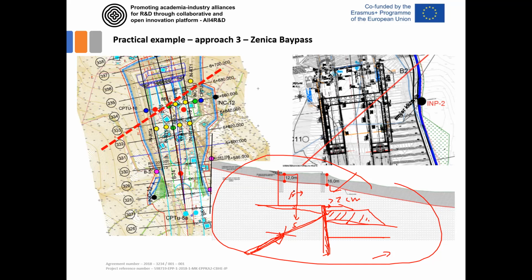So I would always suggest you go with some mean values of the parameters, and it's also in accordance with the design codes that are used, that is characteristic values of the parameters. But for very complex problems like this, like highways passing a landslide, I still think that mean values will not bring the cost so much in comparison to an observational method combined with the most optimistic parameters at the beginning, because there are so many other problems that could